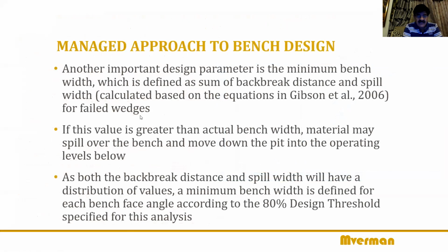Now another important design parameter is the minimum bench width. You want to know what is the minimum bench width. Angle, you know, 49 degrees. Now, how do you define minimum bench width? It is defined as the sum of the back break distance and a spill width.